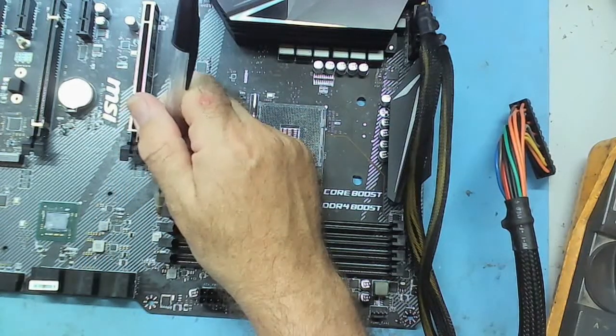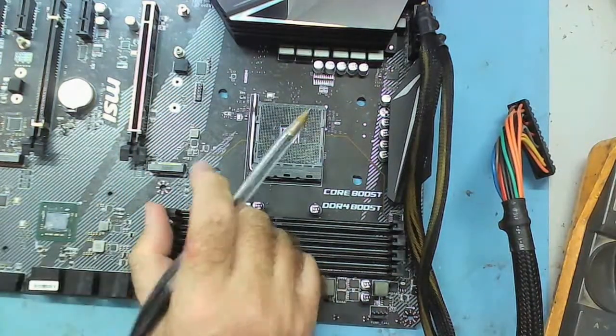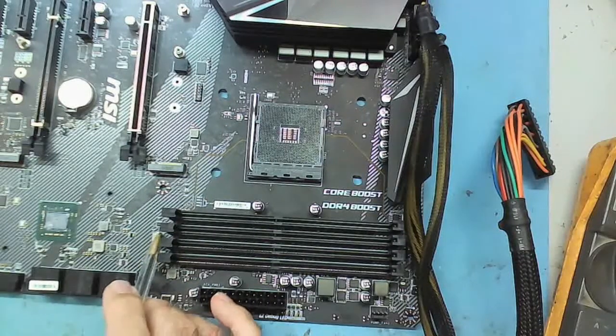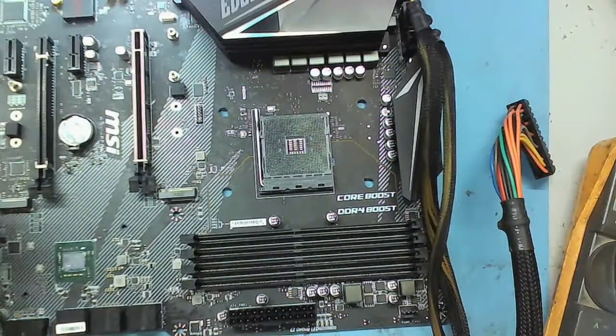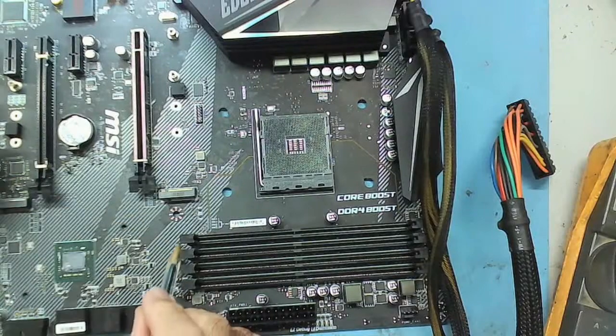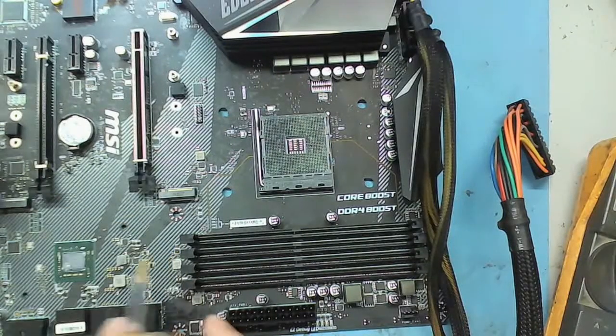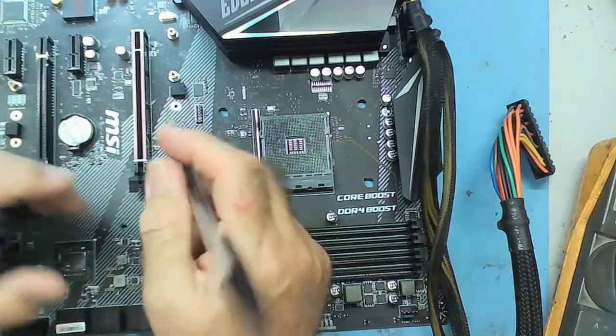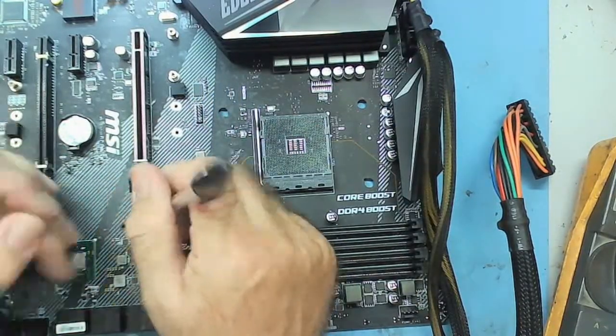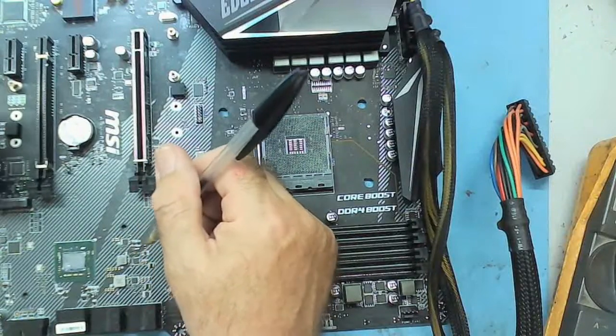Look at the controller. Now that'll be one of two things. That will either be a fixed voltage regulator, so it'll say input 3.3, output 1.8. It'll tell you. If it doesn't tell you that from the data sheet, the output of this will be set by 2 resistors probably, and the ratio of the two resistor values will give you the output. And the data sheet will tell you how to calculate it. And you can measure the resistors and calculate what the output should be.